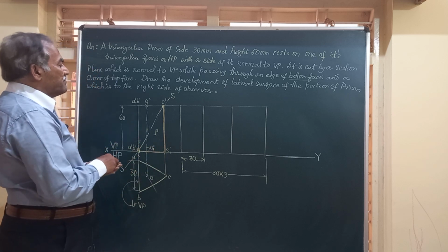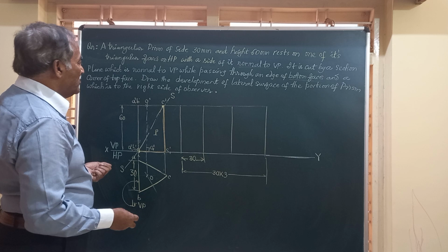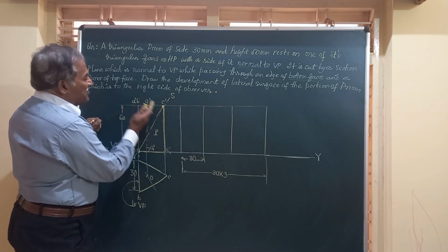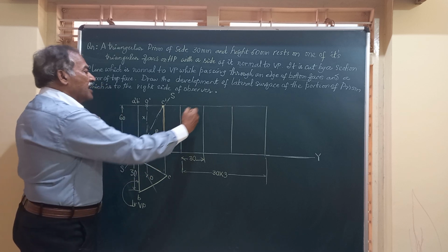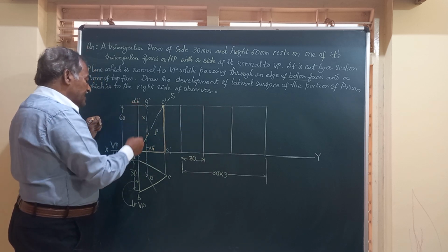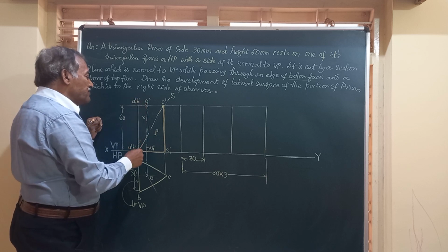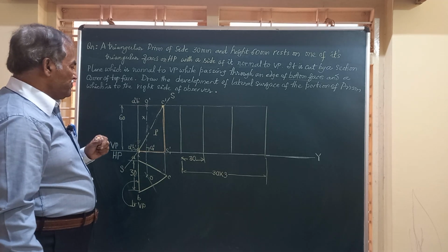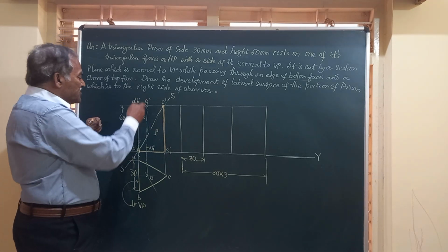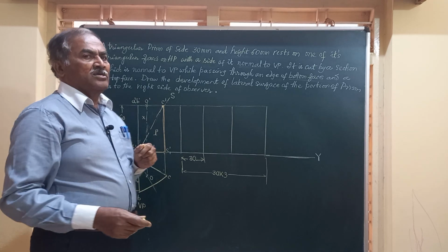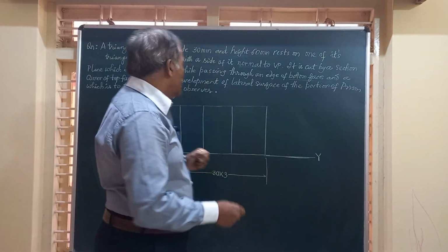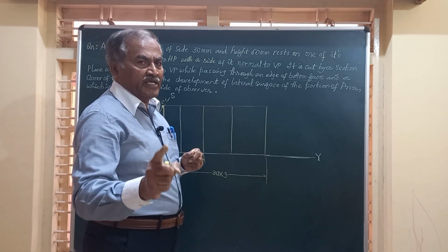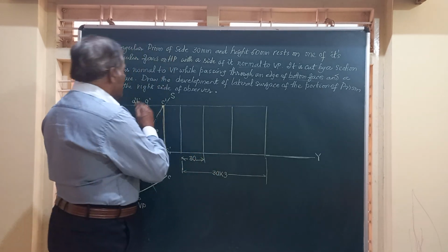So very obviously, if you are just observing the front view, in the development this portion is thrown out above the section plane. So you will not have in the development the vertical edge AA, the vertical edge BB, but vertical edge CC should be completely available. Since these two edges are not existing, you have the choice to commence the development either from AA or from BB only. So let us say I am commencing with AA.